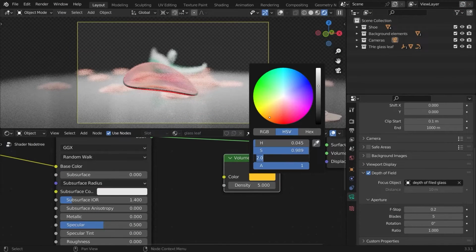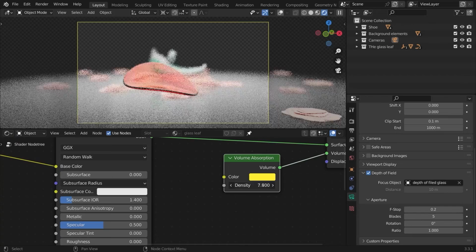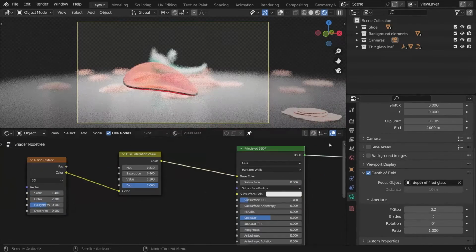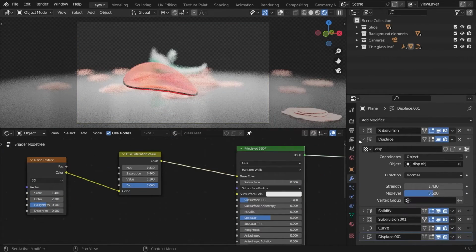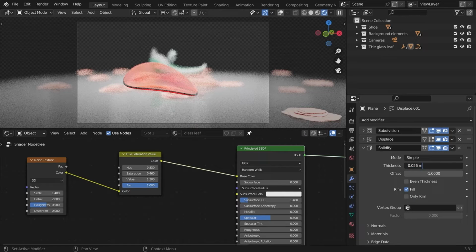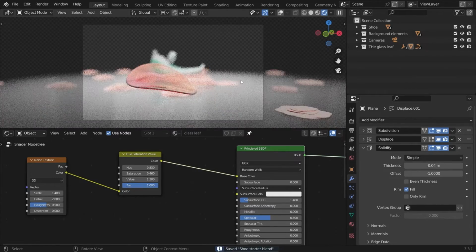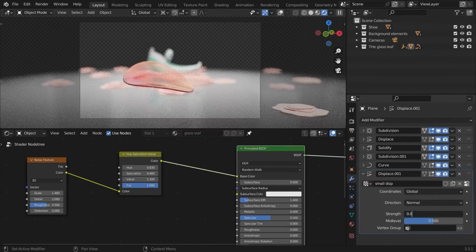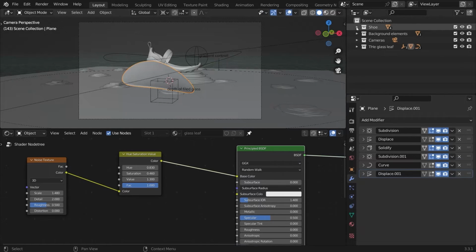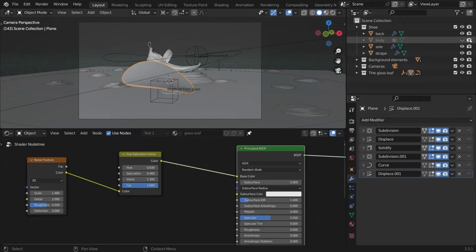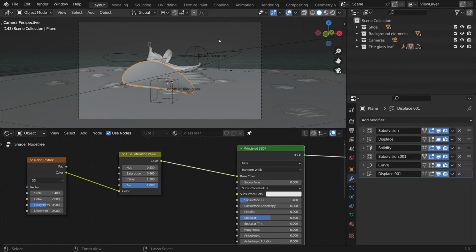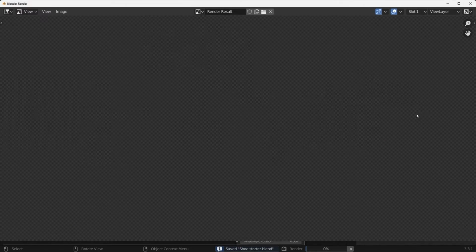Let's make this V to 3 again, bring up the density of it. I think our solidify value is still a little bit high. So go to solidify, and it's negative 0.056. I'm going to make it negative 0.04. Yep, this is good now. The second displacement is 0.04, make it 0.03. That's also good. Then I'm going to go to the shoe collection, and this is our body, so I'm going to turn off the render for it for now. And let's render a frame again.